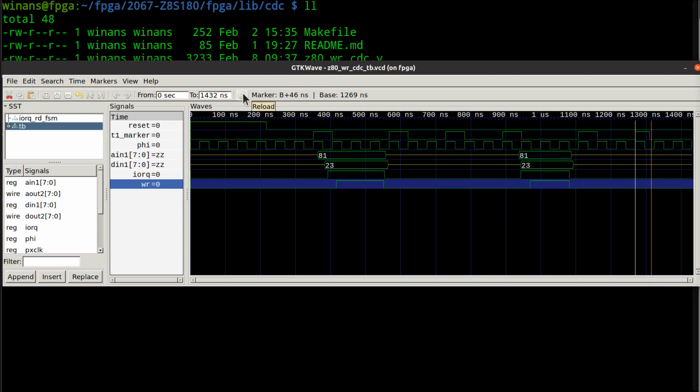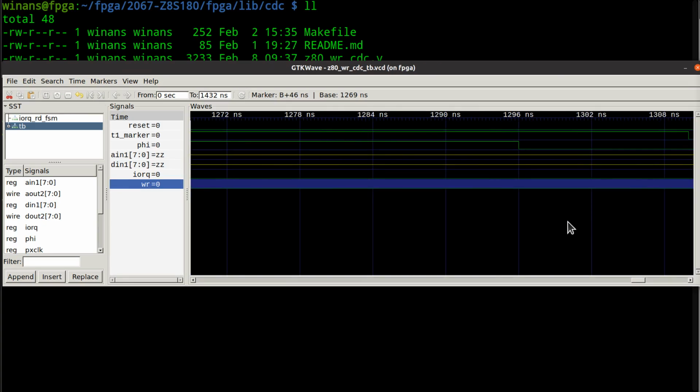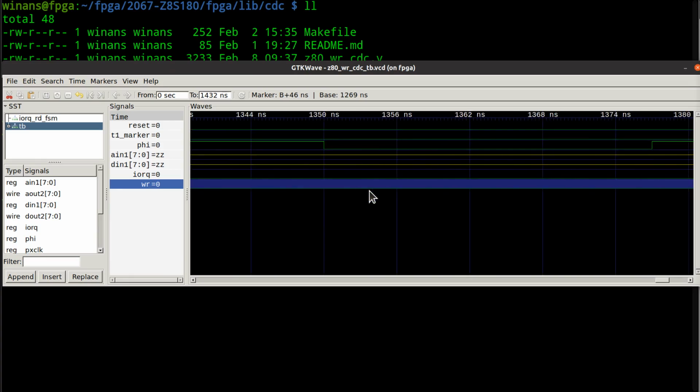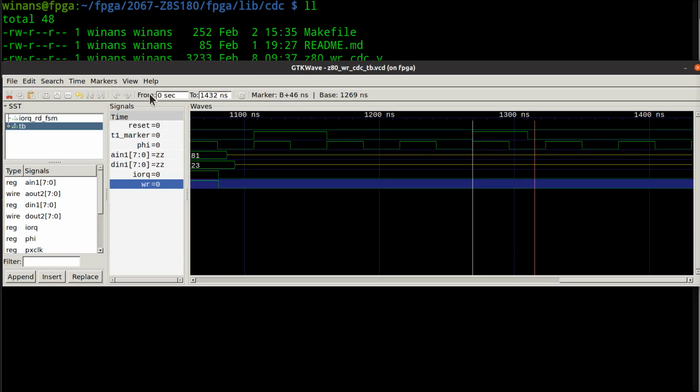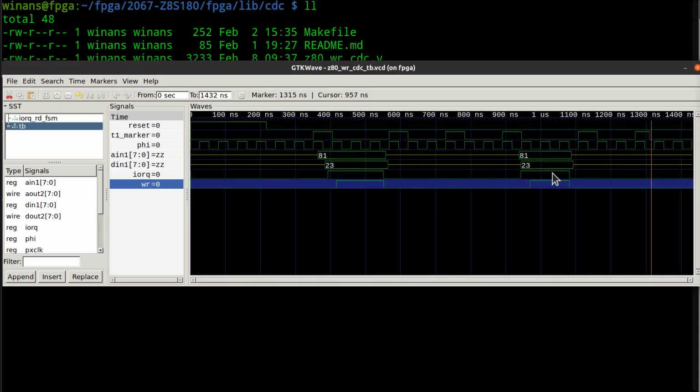This here is a little reload button, which will reload the entire VCD file. And this button over here is the size-it-to-fit-on-the-screen button. And I sized it like an idiot. But the reason it sized it like an idiot is because it sized what I have here. If you do that, get rid of the white marker by just clicking the middle mouse again. If I click it, it goes on; click it on itself or somewhere else, it goes back off. When you do that, just turn it off and then redo this. You see the whole picture.